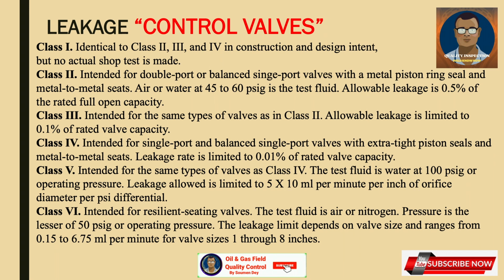Class 5 is intended for the same types of valve as Class 4. The test fluid is water at 100 psig or operating pressure. Leakage allowed is limited to 5 times 10 to the minus 4 milliliter per minute per inch of orifice diameter per psi differential.